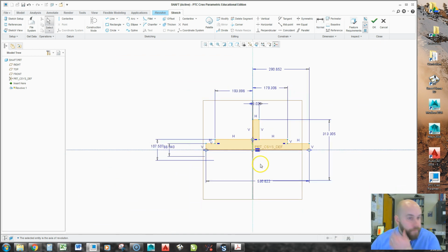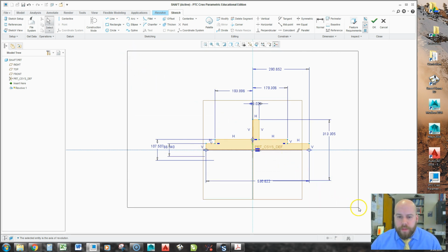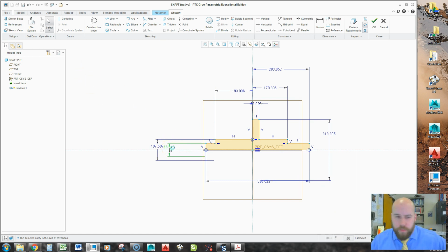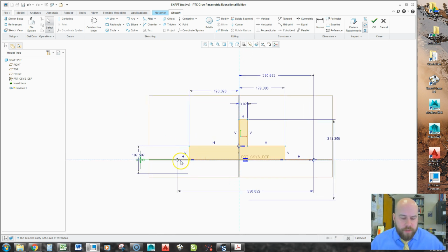I'll zoom out a little bit, and now I can start scaling them down. So what I'm going to do is draw a big box around everything, because right now my numbers are humongous. And if I was to change one of these to the dimension it needs to be, so for example, this diameter is going to be 0.6. Look at that. It's like that diameter is non-existent. It's going to be hard to figure out what I need to change next. So what I like to do is do an overall scale to bring the whole thing kind of down to a smaller size.